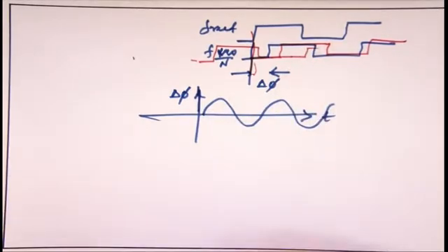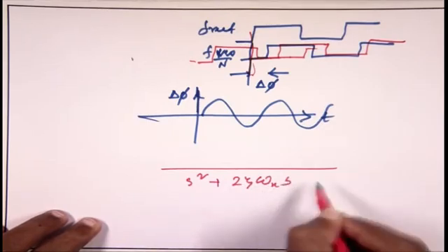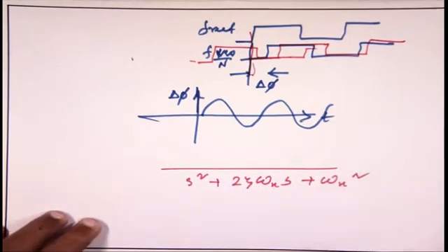The VCO will always find where it has to settle down. It is not going up continuously, but moving left and right, and it will continue. But in the transfer function, if you go for the derivation of Hs by 1 plus Hs, you will see the transfer function looks like a standard, well-known form, with a denominator that has a damping factor.